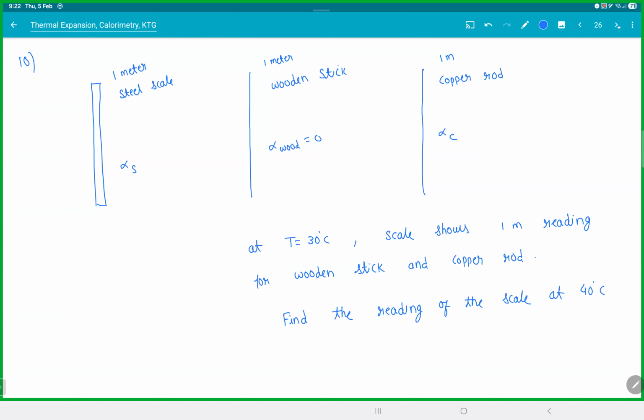Mostly they take around room temperature, 24 degrees. Most of the equipment is designed for Europe and all this stuff. So 24 degrees is the standard temperature. Now, if you bring that equipment from Europe and put it in India, in summer where temperature goes to 42, that instrument which is supposed to measure something will start measuring something else. So you need to maintain a proper temperature in the lab. So the ACs are there for the equipment to give you less errors, and it is not for your comfort.